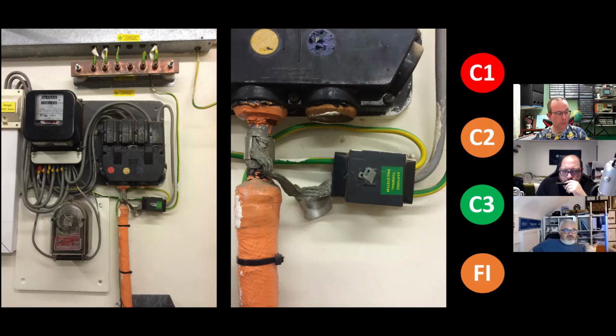So if you've got that copper bar here, which is connected to the neutral and that cable sheath, there could potentially be a potential difference between the two. So that's why they link them. So it's kind of reversing it. It's not taking the TN-S separate from that. It's actually earthing the exposed conductive part of the supply sheath.